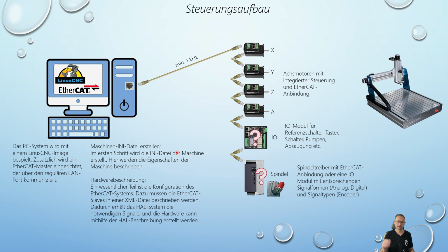And this happens here, in the third instance, with an XML file. Otherwise, when using EtherCAT, the INI and the HAL should be written just as if I were using the whole thing without EtherCAT. But that is my picture of a typical portal milling machine as it could be operated here with EtherCAT devices.